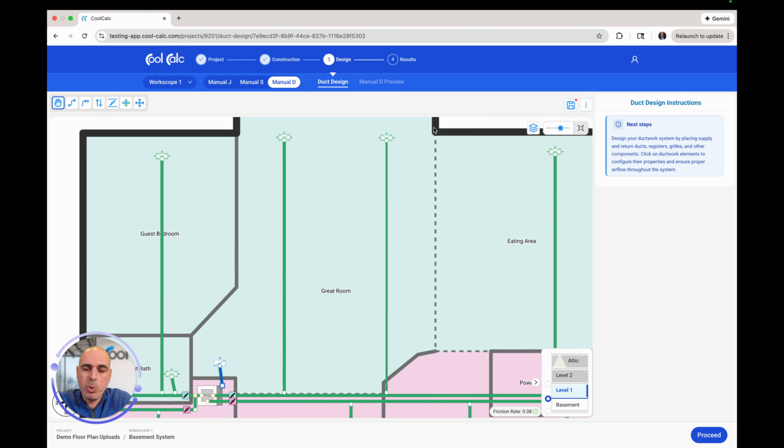So this is why it was important. If you go back and look at the video when I drew this floor plan, you'll notice that wherever there really wasn't a wall and I wanted to separate spaces, I didn't draw a wall. I drew a divider, which are these dashed lines. And what that divider allows for is it now allows this program to know that there's a free air return path from these registers all the way back to this return.